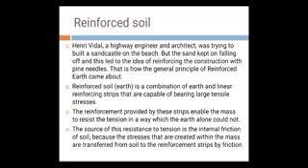The source of this resistance to tension is the internal friction of soil, because the stresses that are created within the mass are transferred from the soil to the reinforcement strip by friction. As the reinforcement and soil form a composite section, the soil will transfer its load to the reinforcement we use, and the friction between them will resist the failure. And these reinforcements are in the form of strips.